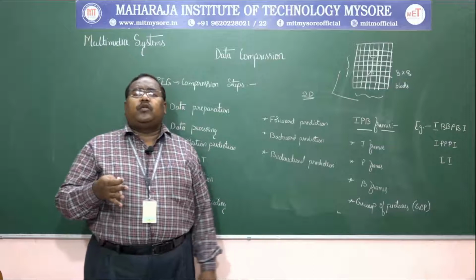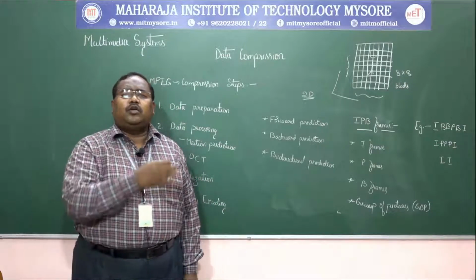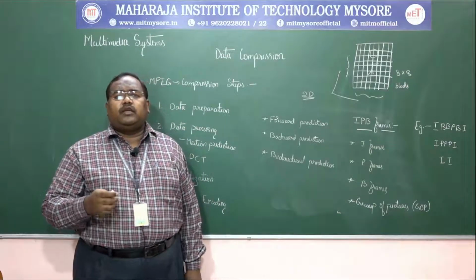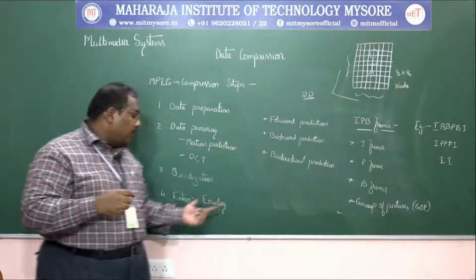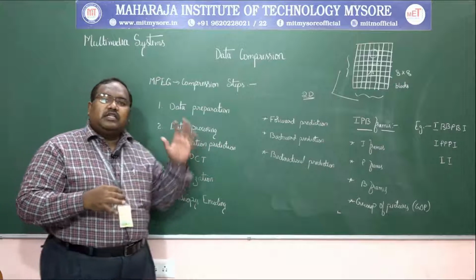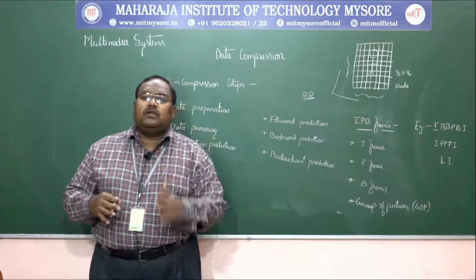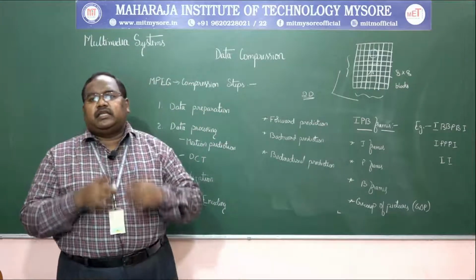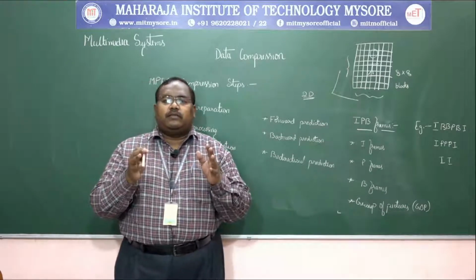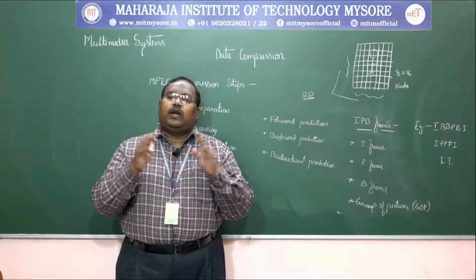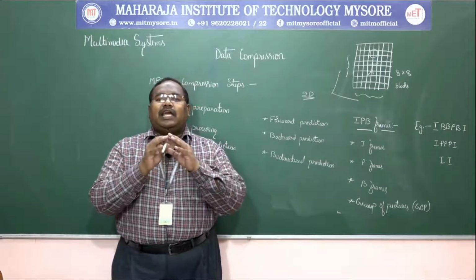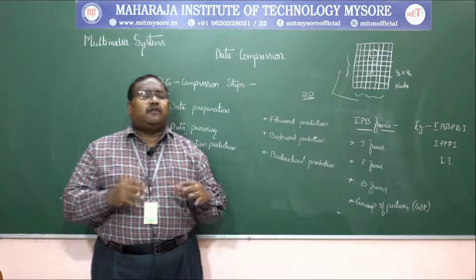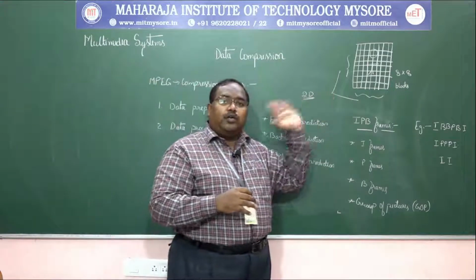What we do here in the entropy coding, because we need to apply the algorithms for efficient utilization. So what we do first in the entropy coding, we convert these 2-dimensional symbols into 1-dimensional series, that is 2-dimensional data is converted into 1-dimensional data. This helps to apply the algorithm effectively, because it's very difficult to apply the algorithms on 2D data.